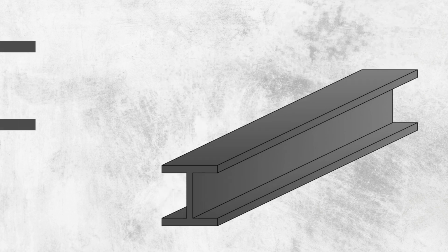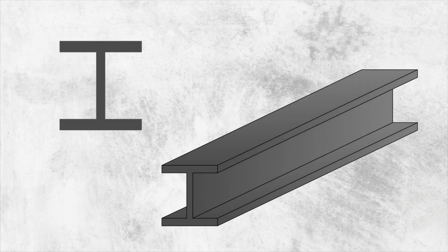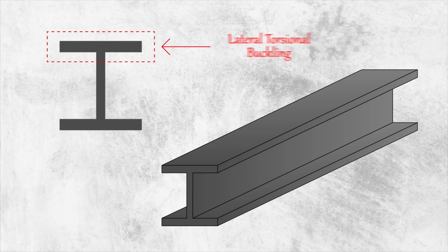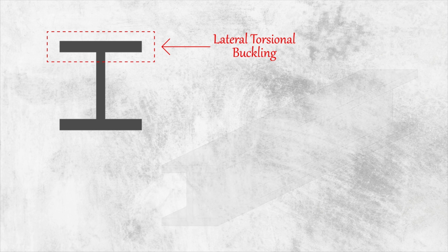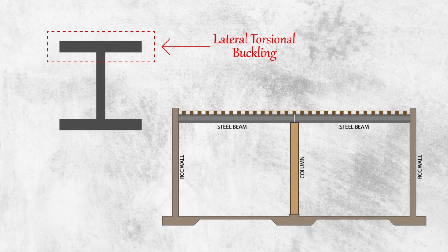Now we design the steel beams, but there is a problem of lateral torsional buckling in the compression flange of the I-shaped section. To avoid this, we continuously brace it with the wooden beams placed on top of the steel beams. In the project statement, the clear spacing between wooden beams is not mentioned, but if we use judgment as per the given figure, it shows many wooden beams on each span. So this indicates that the compression flanges of the steel beams are continuously supported by the basement roof.